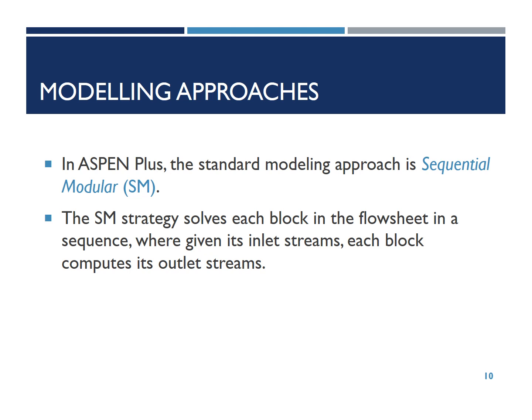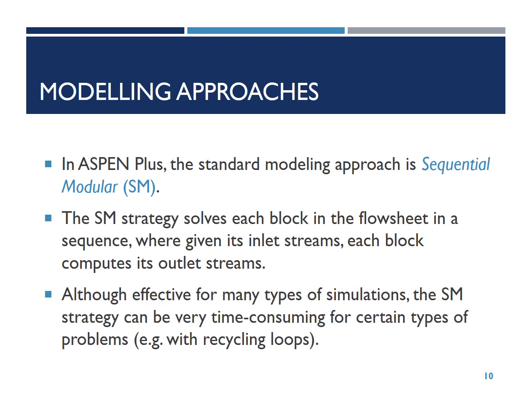When there are recycled streams, flowsheet iteration is required. Although SM is effective for many types of simulations, it can be very time-consuming for certain types of problems. For example, processes with a large number of recycle loops.